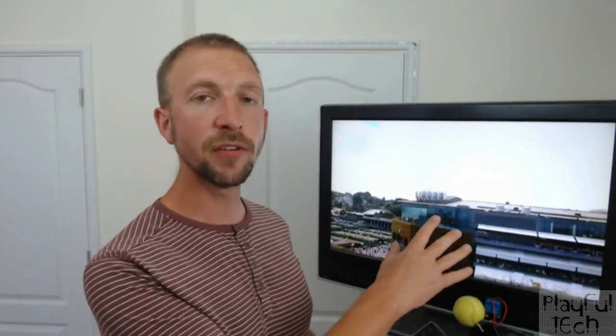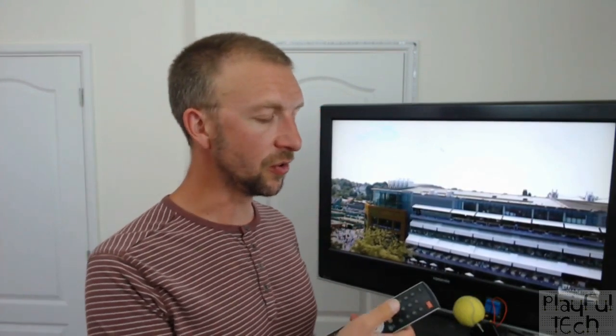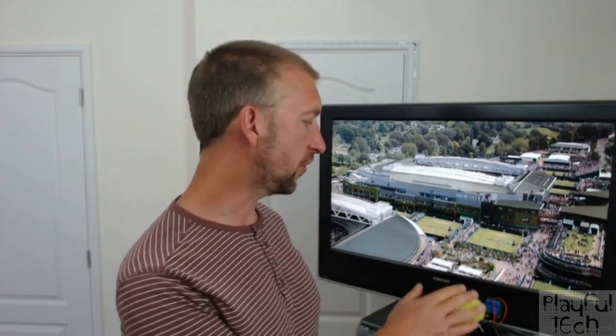So the Arduino around the back is constantly monitoring the pattern of buttons pressed on the remote and the channels which players go to. And that's got a sequence of TV channels saved in the sketch. And when players go to those channels in order, the Arduino will detect that that has occurred, release the relay, activating the maglock, and the tennis ball flies across the room.